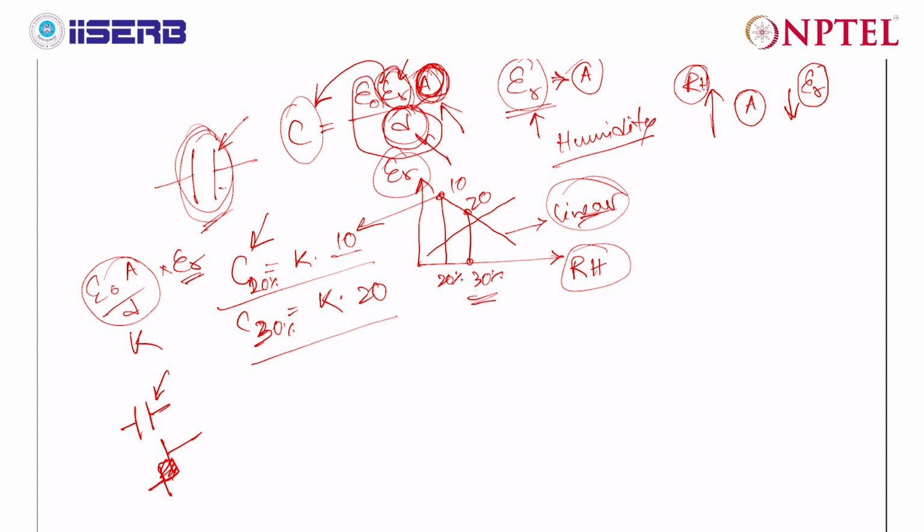For example, if you press from one side, you may find that this particular electrode comes closer to the other electrode. In that case also your capacitance value will change, so you can take advantage of that. However, in all the cases, you need this capacitor arrangement, because the capacitor can directly be connected with an electronic system.